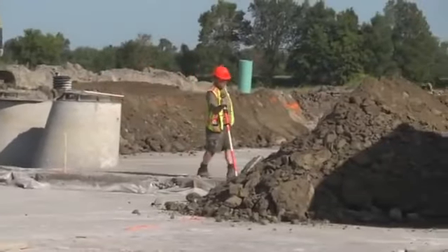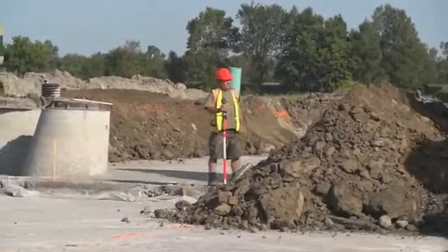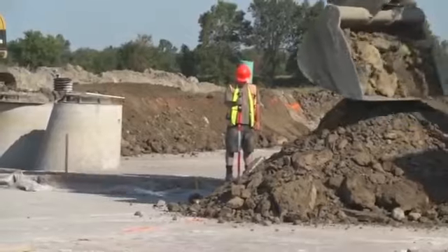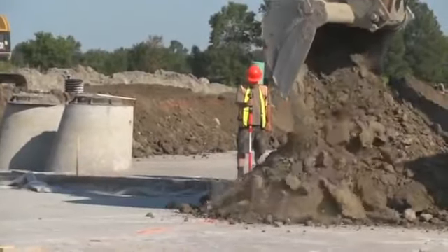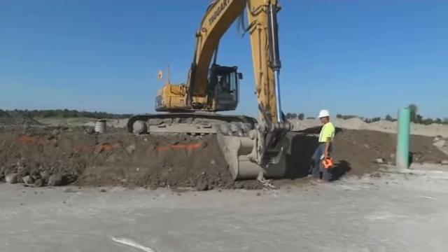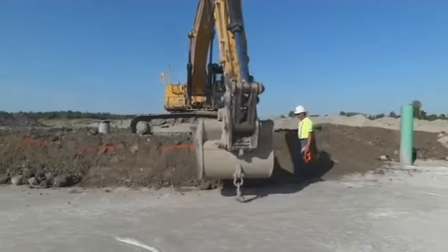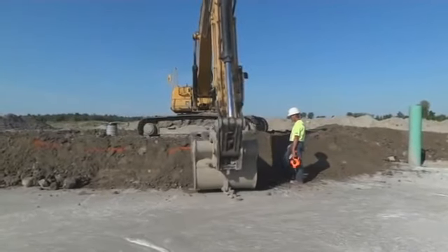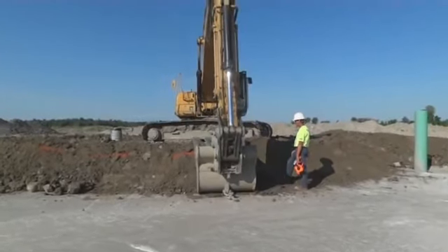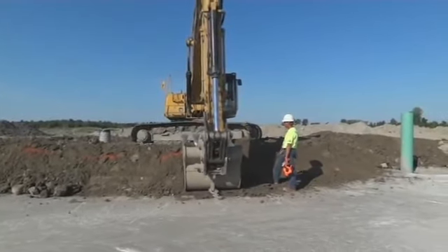The weight of the structure is greatly reduced, which is effective on weak sand and wetlands, and at the same time the thickness, depth of the road foundation is considerably reduced. Cellular concrete possesses liquid consistency, and the roughness of the soil surface is not of great importance. The depth of the ditch is immensely reduced. Cellular concrete protects the foundation from softening in rainy weather.